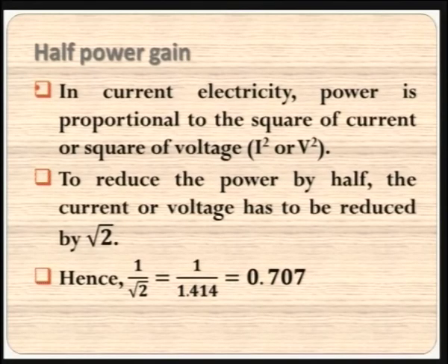But how do we get an increased bandwidth? So, as I said, the gain is to be sacrificed for getting the increased bandwidth. In the design aspect itself, we can have a control over choosing the bandwidth. Nevertheless, in the consideration of the frequency response curve, customarily we draw a line at the half power gain point and then take the bandwidth.